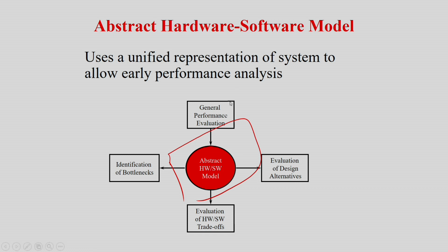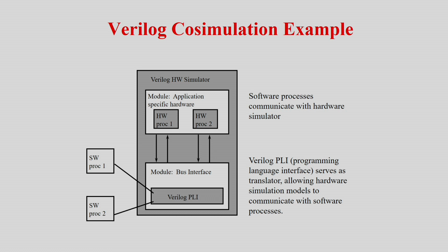So you can do a lot of general purpose system evaluation, you can do evaluation of design alternatives, you can do evaluation of software hardware trade-offs, identification of bottlenecks or bugs. Everything is possible, but I require a simulation version of this, which is the main challenge. So how have people tried to do it? They have something called a Verilog hardware simulator.